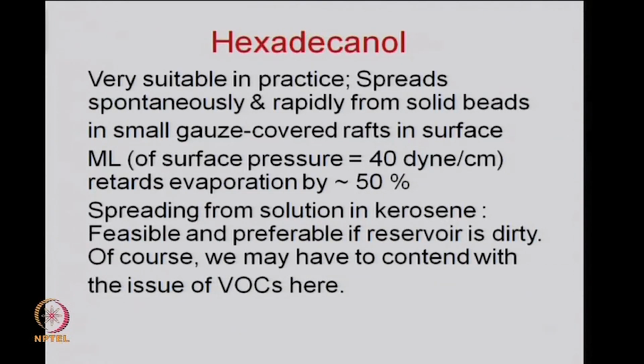Sometimes, if the reservoir surface is heavily contaminated, then we might need to aid the spreading of hexadecanol by using kerosene. So, it is possible to dissolve hexadecanol in kerosene and then the solution can be made to spread rapidly. One may of course have to deal with issues like VOC emissions. Presumably the quantities of